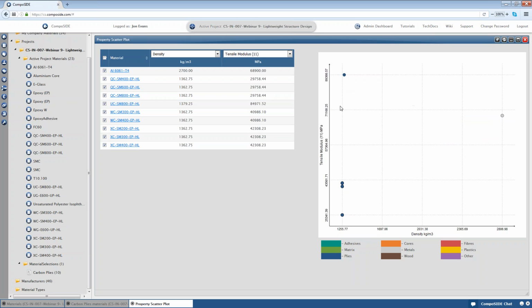So quadraxial ply will be a very good starting point for this. It's got equal fibres in all directions, so very, very easy to design with. We can get a very good first design out of this. Okay, so let's say we're going to use the quadraxial first. Then what do we need to do?